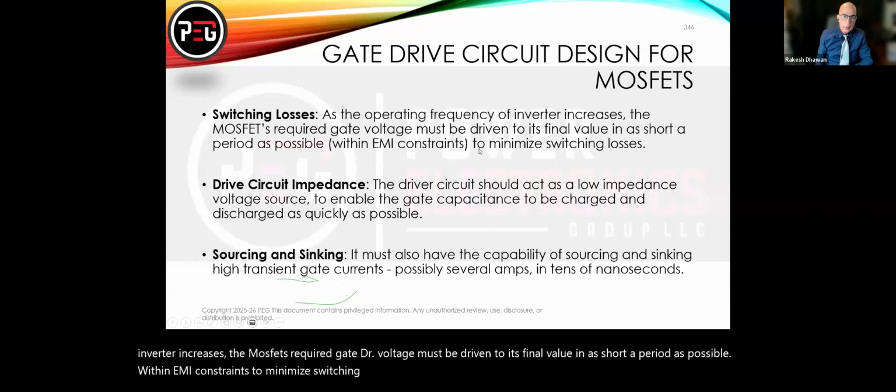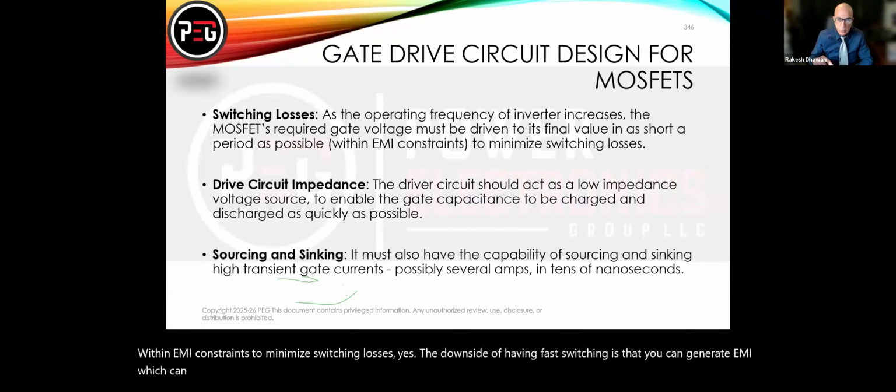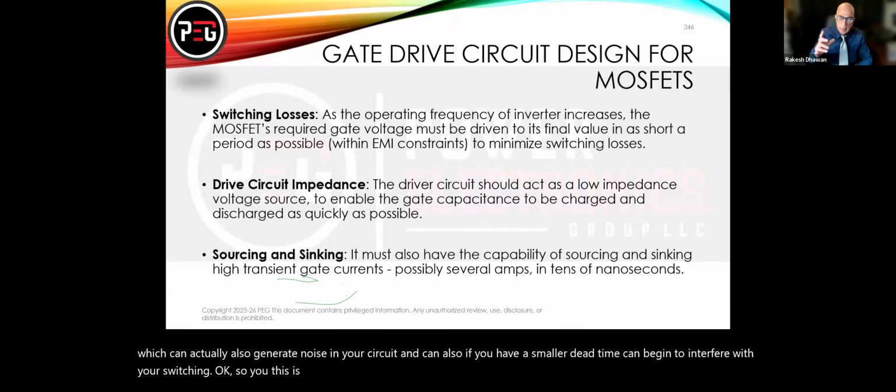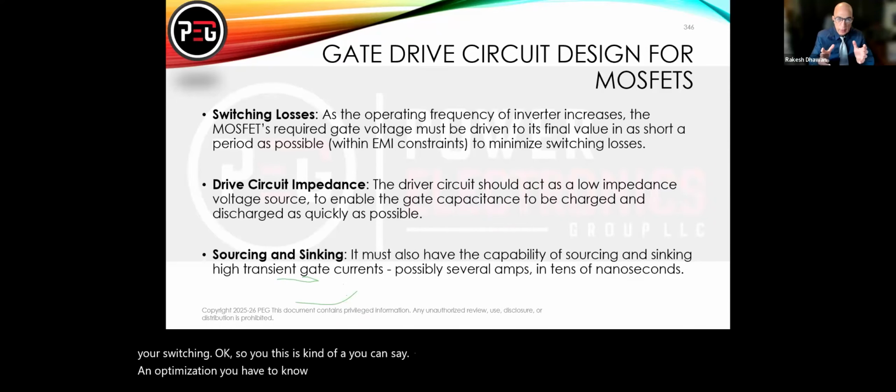Yes, the downside of having fast switching is that you can generate EMI, which can also generate noise in your circuit and, if you have a smaller dead time, can begin to interfere with your switching. Okay, so this is an optimization you have to know about if you're having issues with your gate drive.